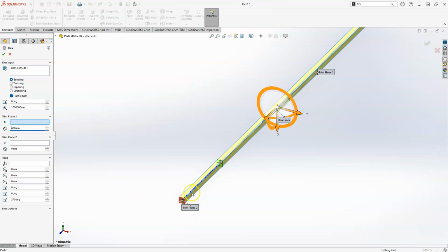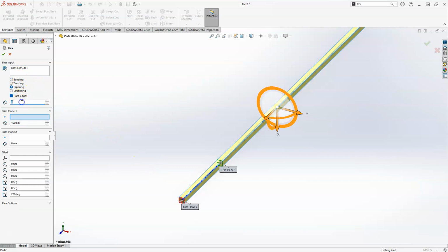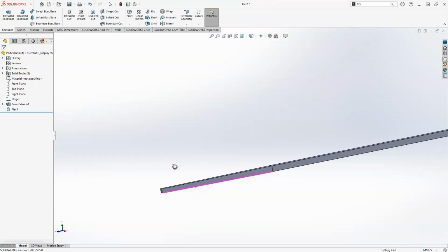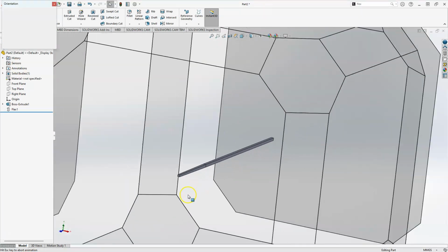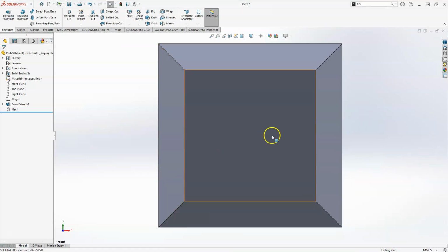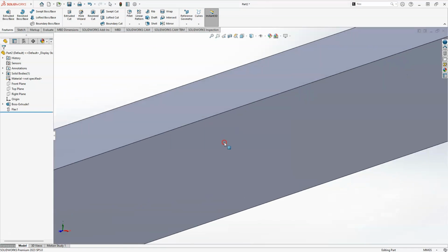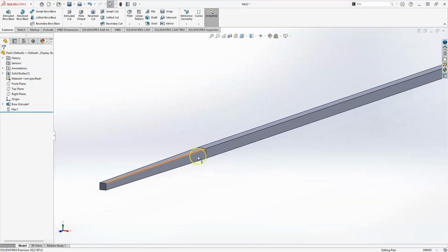It's all the way here. I'm going to taper the last end of this one. And out of this feature, I would select tapering, and the slope is negative 20%. So essentially, hit OK, and you will see that the end is going to taper. Actually, if you look at it from this angle, maybe it's more clear. Yes, that is the profile of the taper, and this is the one that tapered the last 100.